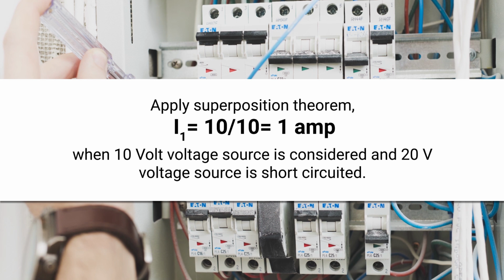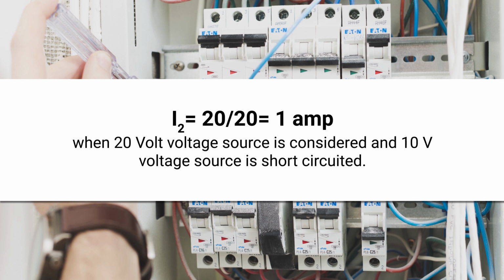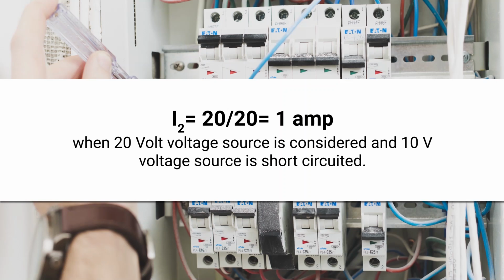Now you consider this 20 volt source, then what will you do? You will replace this 10 volt source by a short circuit. So now how will current flow? Again this current will flow through only this branch. Why? Because this is short circuited and this is also short circuited. So the equivalent resistance of these two branches is equal to 0. So net current will flow only through this path. That current, you can say, is current I2. So I2 is equal to what? 20 divided by 20. So again it is 1 ampere.